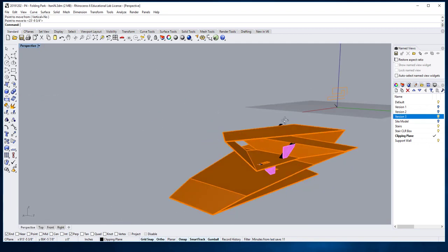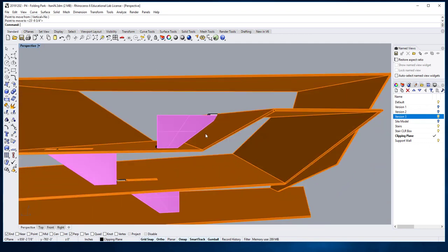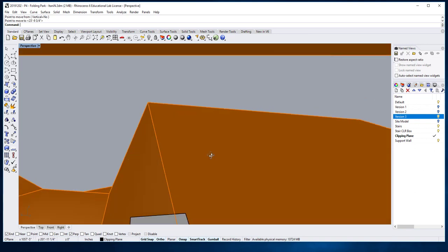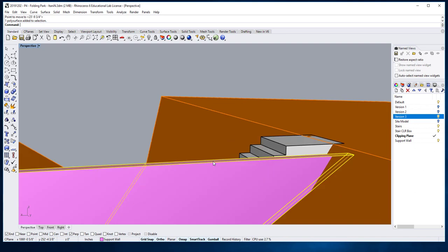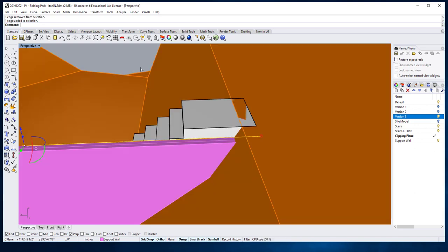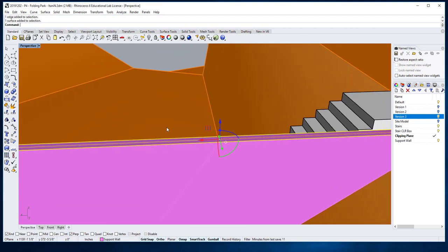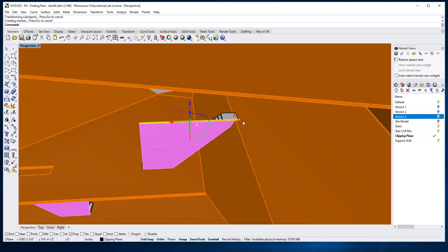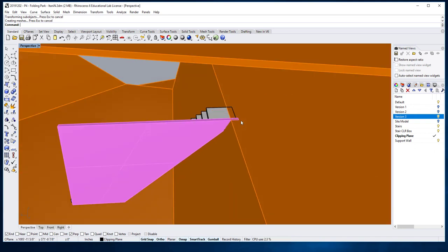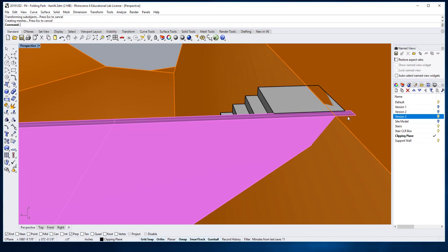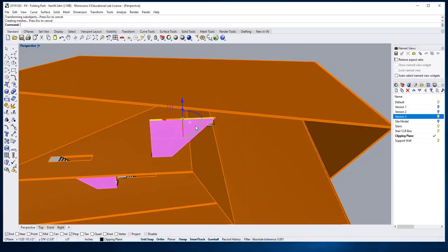Just don't forget to come back and trim that away from that, because see how it dies into this condition? First of all, you need to lift that wall up, right? Right, and you need to lift that up 9 inches. There we go. So now the wall actually aligns with that. I'm going to do something different though. I'm going to take that up another maybe 42 inches so it acts as a guardrail as I'm coming down here. 42 inches. Okay.